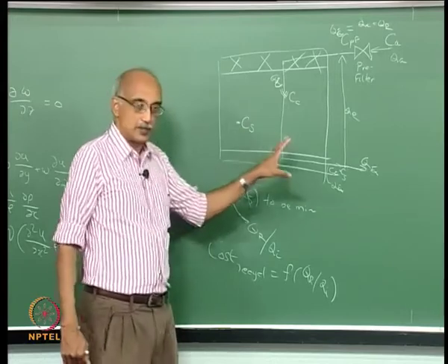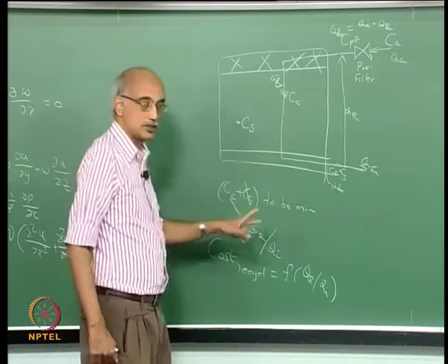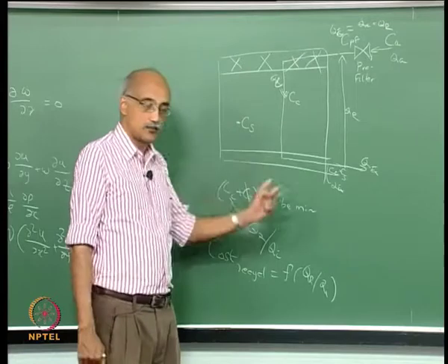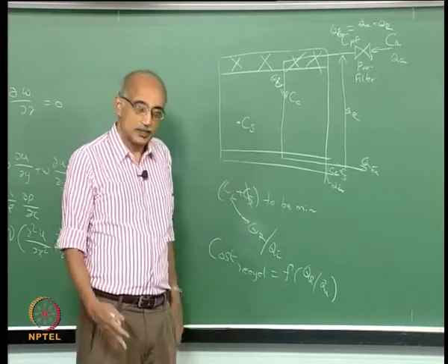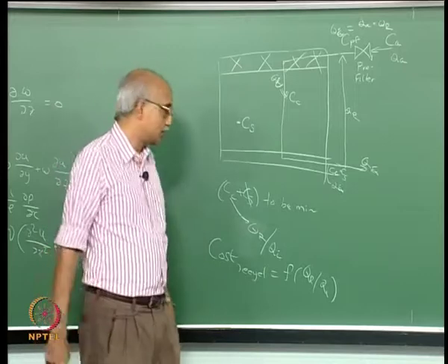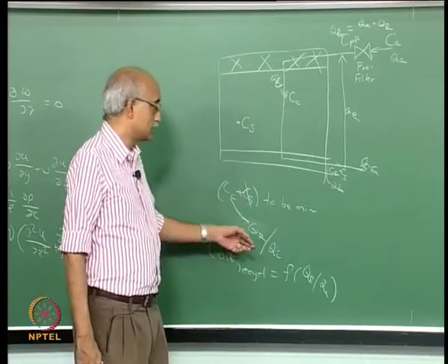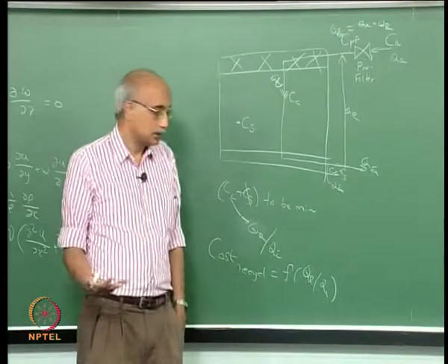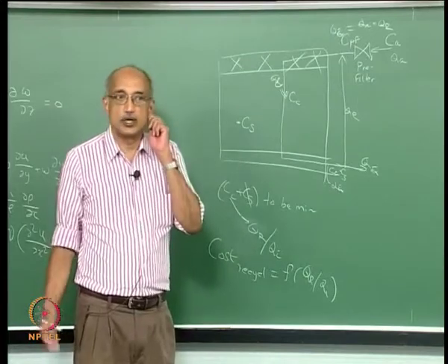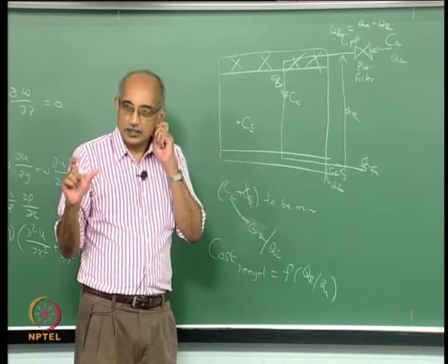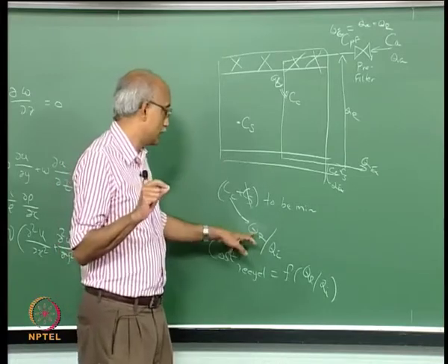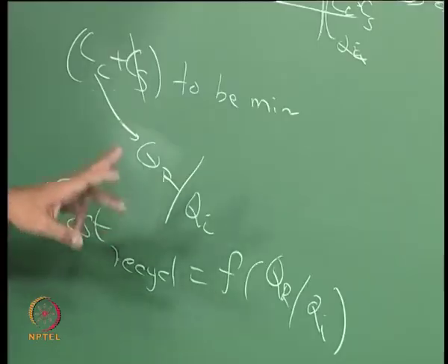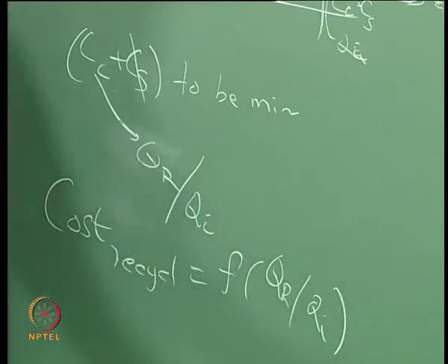Now if you do a simple mass balance on this, you can establish this relationship, right. Using this loop you can actually calculate Cc as a function of all the other parameters in this model. So I encourage you to do that. I think it is a good exercise to set up the relationship between Cc and QR, and then try to do this as a minimization algorithm. Take dCc over dQR equated to 0 and understand the conditions or the value of QR which gives you a minimum in Cc, and similarly we can establish the cost is essentially going to be a linear function of the